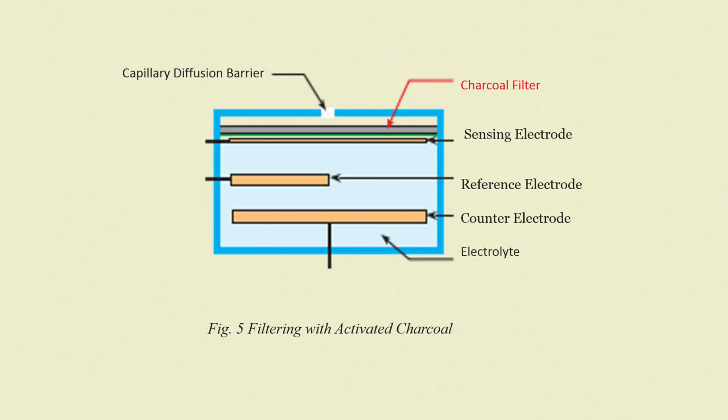So, one has to really worry about electrochemical sensors going out too dry. They are all mechanical defects. Sometimes they go too dry, etc. Sometimes there may be other gases which may react, giving you higher or lower results. So, that also is not desirable basically. So, I had shown you this figure and then I had stopped here.